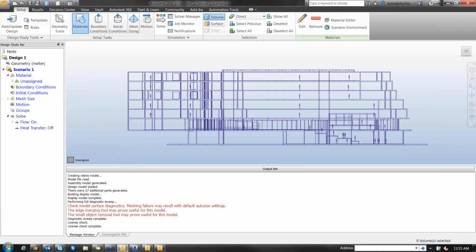So I want to just go back to what Scott was asking about the interference removal. What he was actually getting at was something I hadn't thought about in a while, but it's the prep tool that loads up when loading in from Pro Engineer or Creo. So there is an interference removal tool there, but that's a legacy thing because we didn't support Boolean operations reading in geometry from PTC. So there had to be some sort of tool so you could identify and clean up interferences before you launched it, otherwise it just wouldn't work. So that is a unique workflow coming in from Creo. Okay.